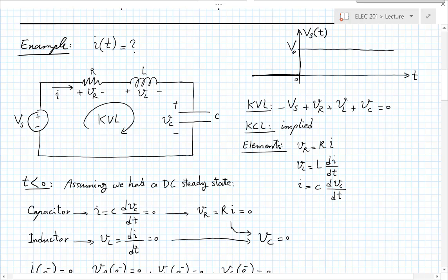For instance, if you have 2 capacitors that can be combined to be replaced by 1 capacitor, then you would not see this. Or you could have a circuit that is complicated enough that looks like it has an inductor and capacitor, and you would expect this, but maybe something is shorted out somewhere that you won't see this, right? So yes, for a simple standard circuit, you would expect that if you have an L and a C, you would see this. But I don't want to generalize it too much.